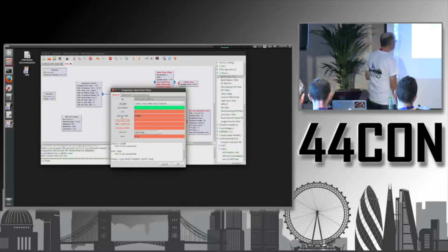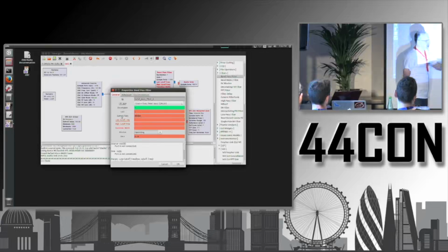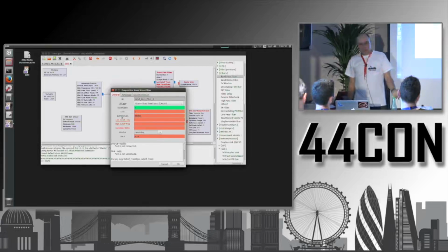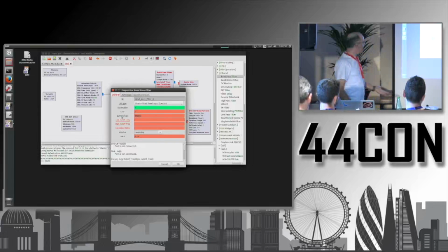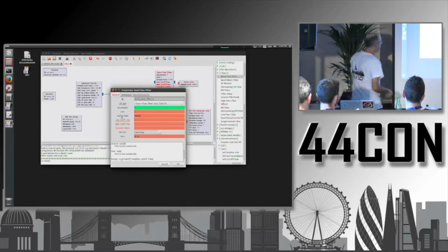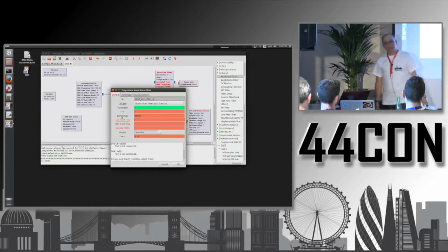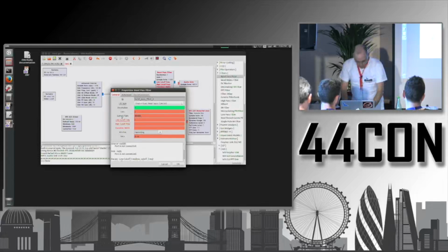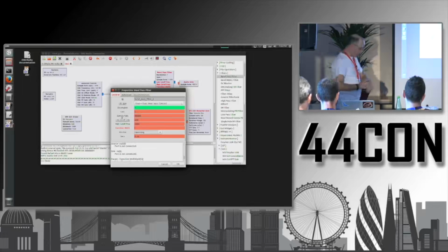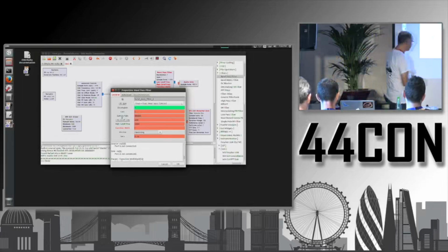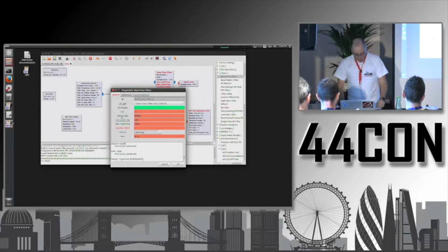And now we are going to set this filter to simulate the frequency characteristics of the old analog telephone line. Okay? And that was between 300 and 3000 hertz. So you can put in here 300 and 3000. And then for the transition width here, you can put in something small like 10.